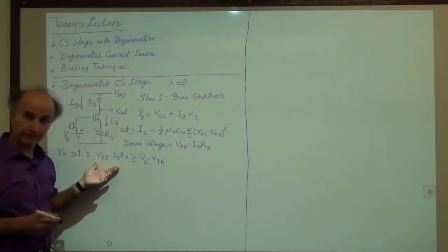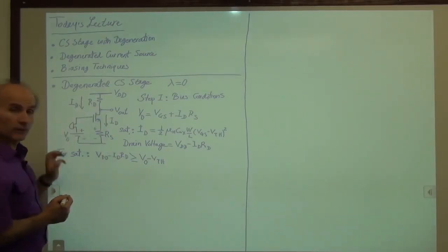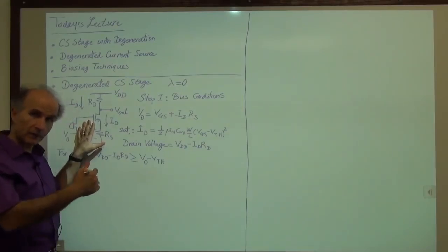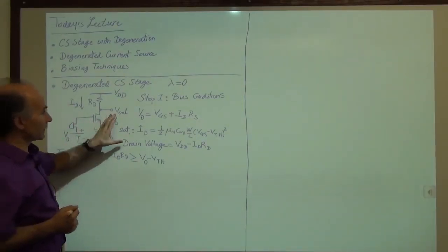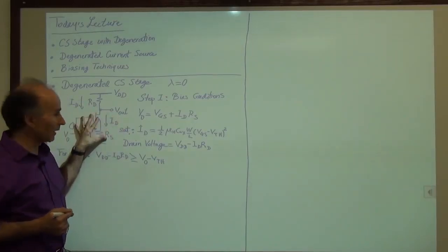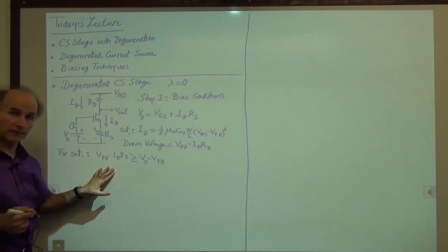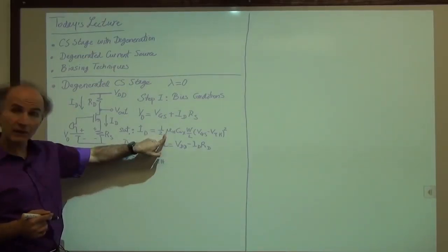If not, not. So when we are given the circuit with actual values and the parameters of the MOSFET, mu n Cox, VTH, W over L, then we proceed. First, we assume it is in saturation and calculate these things. And then we go and check this result. If this result doesn't hold, it means that this assumption is incorrect, right?